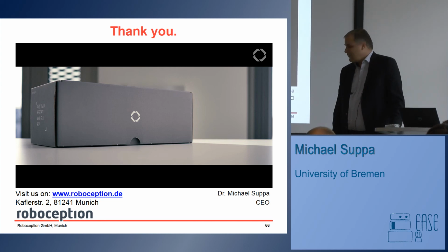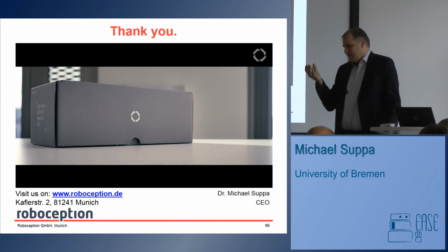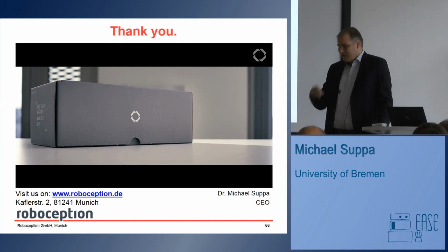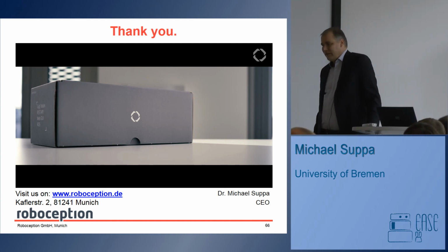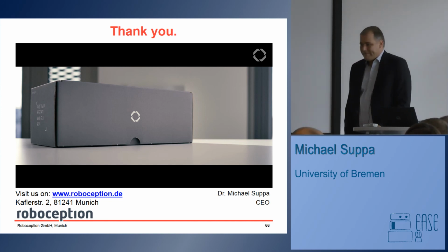We will do that definitely in future, but right now we don't have a sensor that we can really use for that. Because it's always hard to distinguish between slipping, and whether the grasp is good or not. Right now we are mostly using just the motor current to detect the force, and that's it. We don't know if something is slipping.